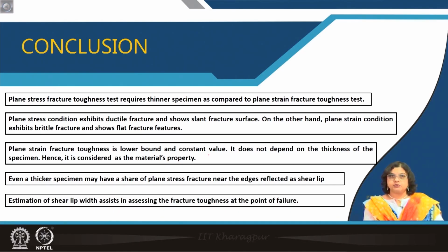Also, if we can assess the shear lip width or shear lip depth, we should be able to find out the fracture toughness at the point of failure. We can determine that value.